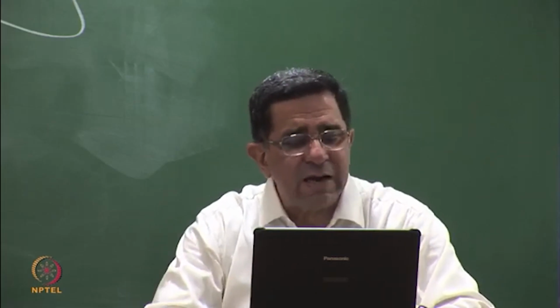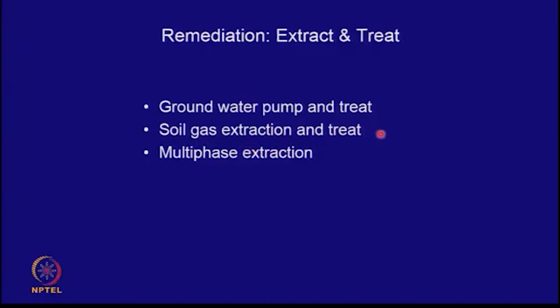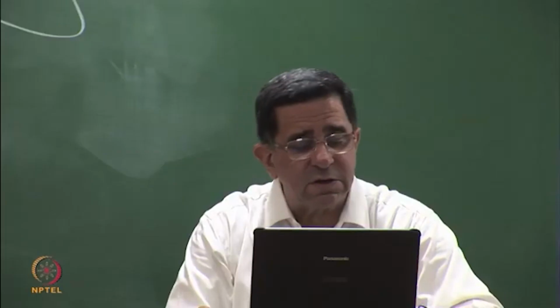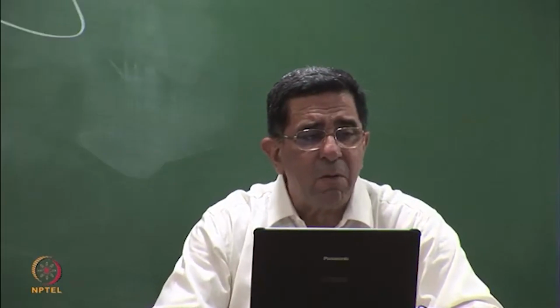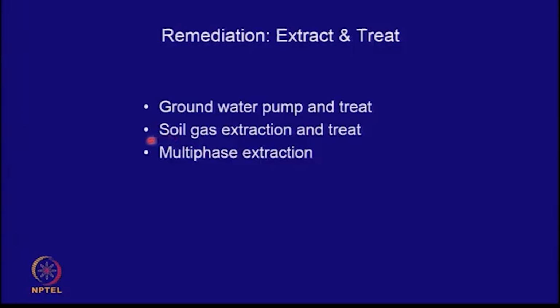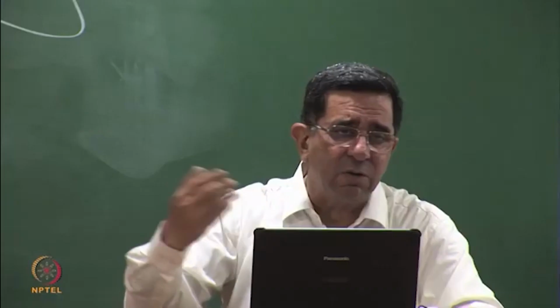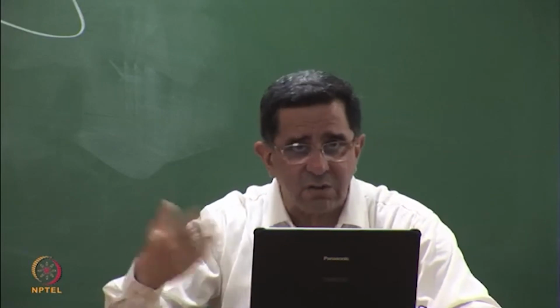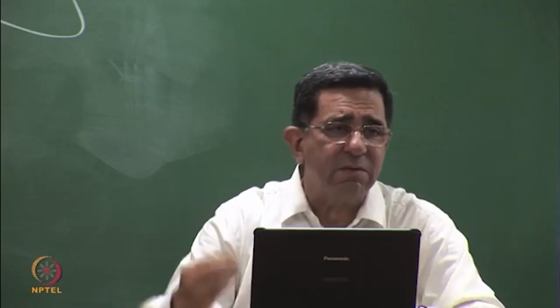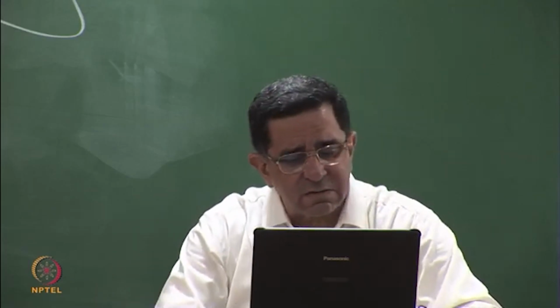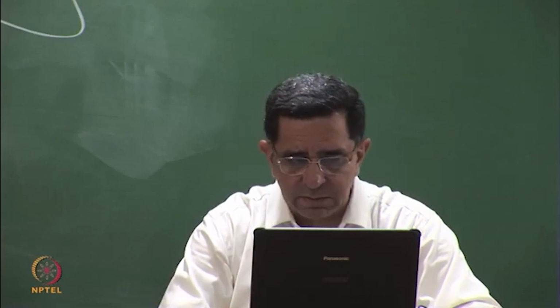So soil gas extraction and treatment is also one of the solutions which is adopted in most of the petrol stations. In some complex cases, you have to do multi-phase extraction. That means you have to separate out the gas and the liquid and the solids and treat each one of them separately. But this is a rare case, so we will not get into this at the moment.